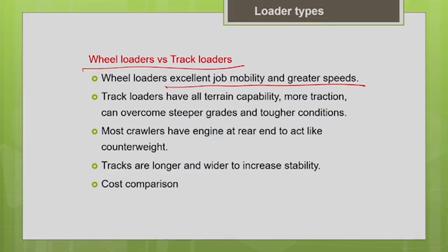But the main advantage of track loader is it has all terrain capability. That means it is suitable for very poor underfoot conditions also. It can climb steeper grades for a very rocky terrain or clayey terrain. Even in very poor underfoot conditions, it can give you better productivity with the track loader.